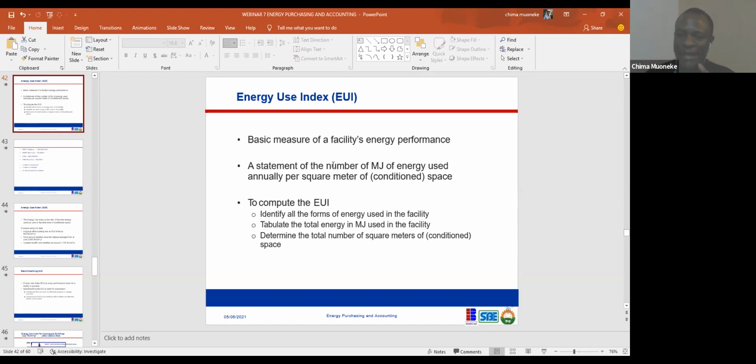That's one. Two, there's a caveat here. It says conditioned space. So even if you're comparing hotel to hotel, the floor area that you're considering is the air-conditioned space, not maybe the atrium or a veranda that's exposed. It has to be the conditioned side, the area where you have climatic control, where you want to control the space for human habitation. So it also tells you the kind of area to look at: not all the floor area, but the conditioned floor area.